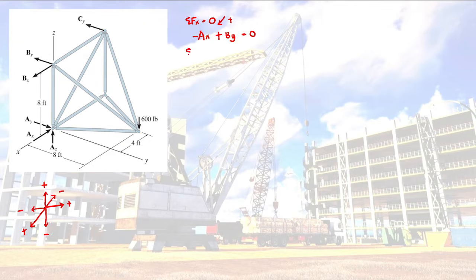Then, ano pang equation? Summation forces y is equal to 0. So, ano yung y ko dito? Going to the left, negative. Going to the right, positive. So, we have my AY here, this one, this is positive. So that is AY positive. Then what else? We have the BY. Our BY here is negative because going to the left, BY. Then we have your CY that is also negative. CY is equal to 0.